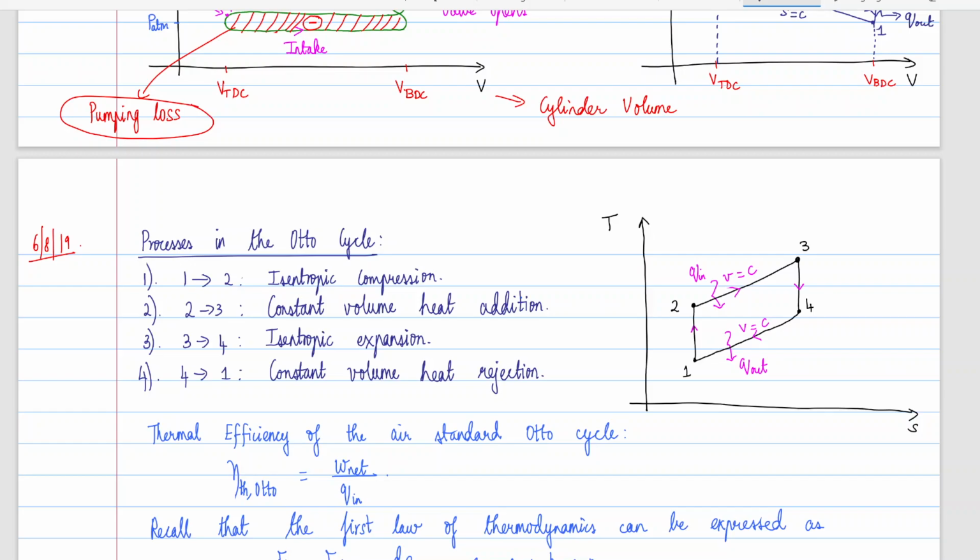But I think you can find really good references on that to get started with understanding. The idea there is to have compressed air at very high pressure, mix it with fuel, burn it, and use the kinetic energy in the exhaust to run a turbine. The same turbine ends up rotating the compressor. So this mechanical energy transmission cycle continues. The energy from combustion is utilized in two ways. First is to compress more air, so a positive feedback is there. And secondly, the air pushed out would generate the thrust.